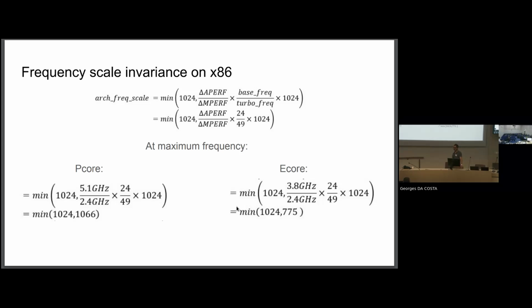And this is why E-core, instead of having 1, has a 0.7. I'm waiting for the point, essentially, because of course this is not going to work for hybrid. It was never meant to. So that is the reason I said that for P-cores this code works reasonably well. Even for this platform, I saw that the 4-core turbo ratio and the 1-core turbo ratio are not that much different, meaning it worked reasonably well for P-core.